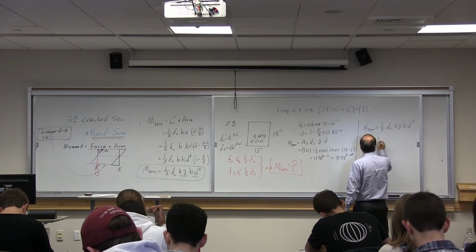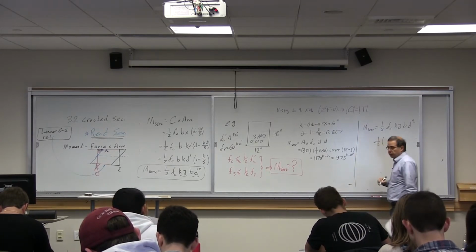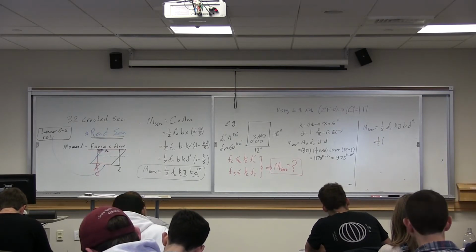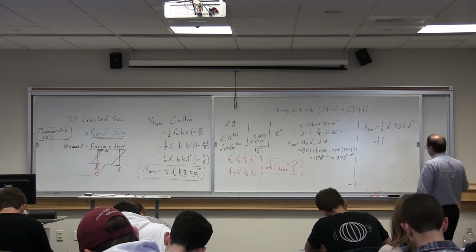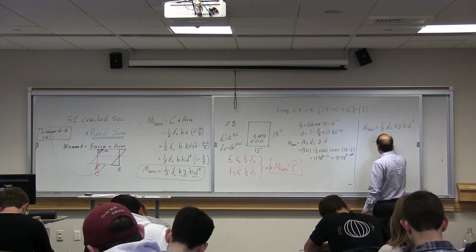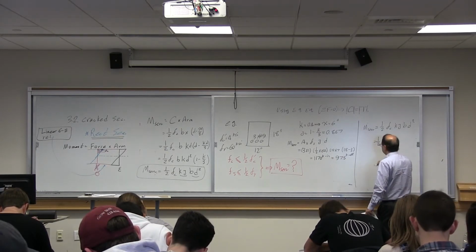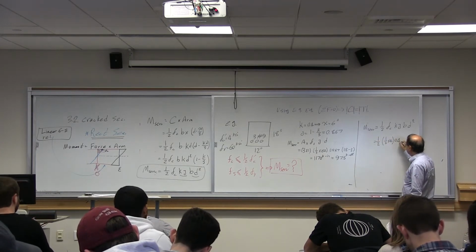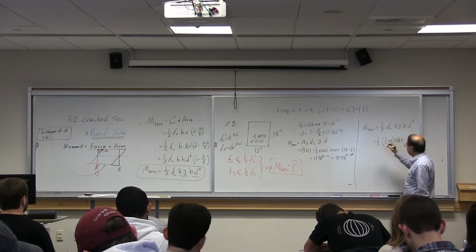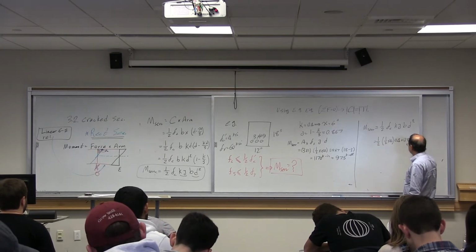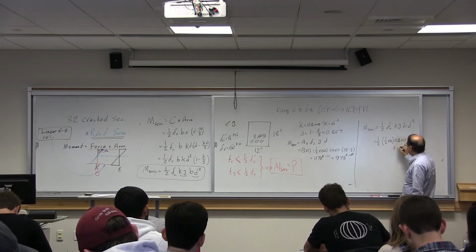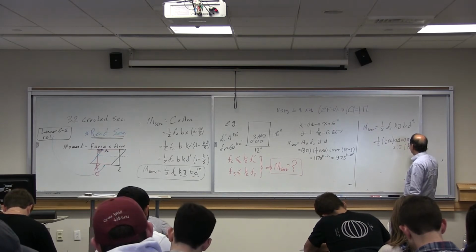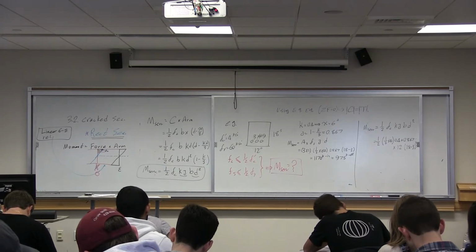We want Fc to be limited to 1/2 of F prime C. Therefore, I replace Fc with 1/2 of 4. K is 0.4. J is 0.867. B is 12. D is 18 minus 3, and we need to square it.